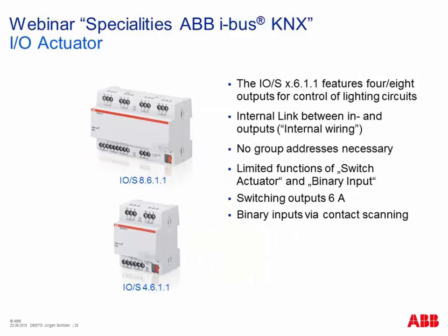And to this family of Room Masters belong, in my opinion, also the I/O actuators. Very similar to the Room Master, especially to the Room Master 4.1. Only 8 inputs and 8 outputs, or half of it, 4 inputs and 4 outputs. But with less software functionality compared with the Room Master. So we do not have these scenarios, for example. We do not have any light scenes and other specialties, logical functions, for example. It's very simple in terms of application of parameters. Of course, also reduced in costs.